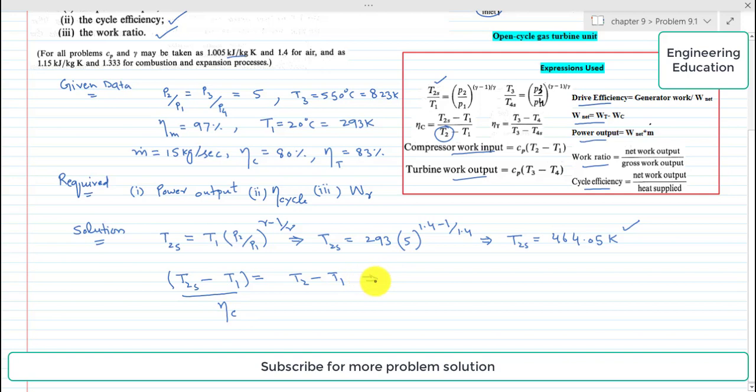So rearranging it for T2, T2 will be equal to T1 plus T2S minus T1 over compressor isentropic efficiency.